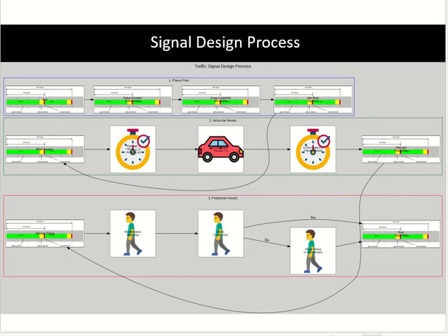So once you have calculated the green time, you are done with the signal design for the vehicles. The next item in the process is to check for the pedestrians. The pedestrians will cross the road. Are you providing them enough parallel green time? Parallel. So if the pedestrian is going in this direction, he needs green time there for these vehicles. Fine. So first of all, you find out how much time the pedestrian needs. The pedestrian need depends upon his speed and what?